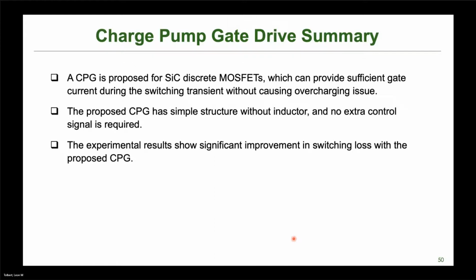Yeah. So I'm sorry, I forgot to mention my name. My name is Fredrik Allerstam, and I'm with On Semiconductor. The reason I ask this question is because you brought up these ratings, which are sometimes much more narrow on the silicon carbide MOSFETs. And we, from our side, making the power switch, are interested in where we should put our focus in improving the device. Do you see a great benefit from us making a device which has a broader negative rating, say that can go to maybe -15 or something like this?